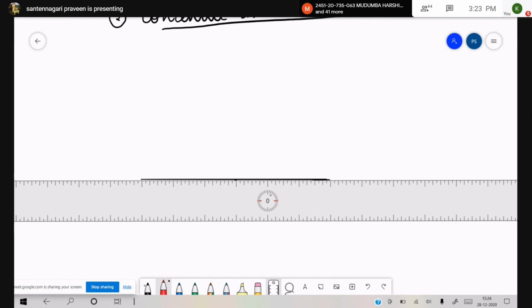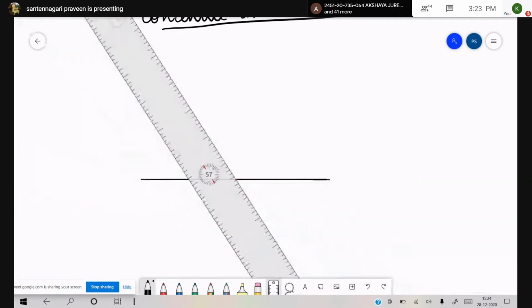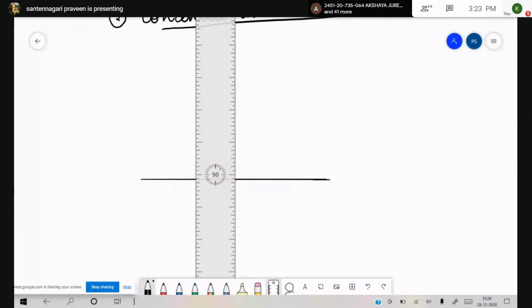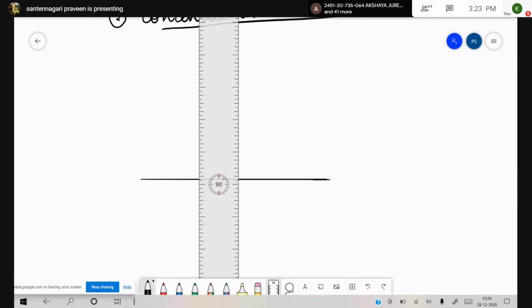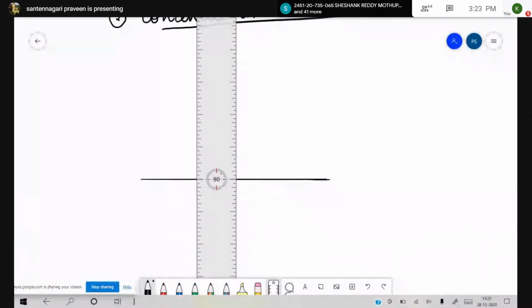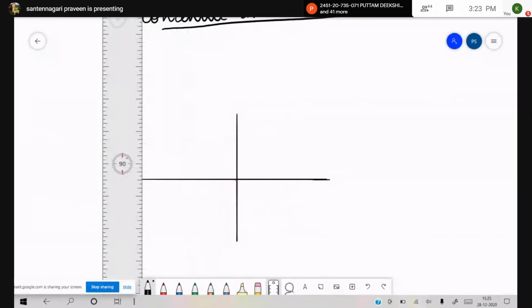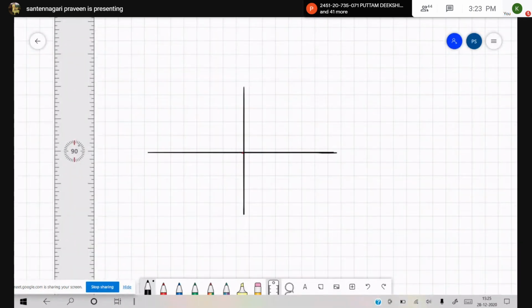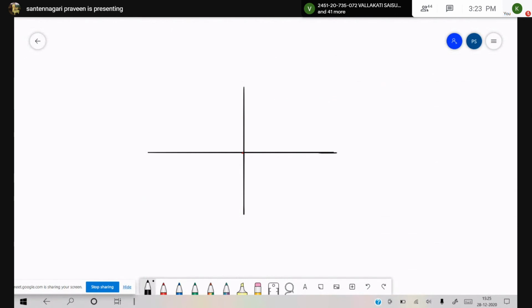This is your center point. So from here, the rest. Place this in the center. Your first half of your minor axis from here, and the rest from here. This is a way to draw your major axis and minor axis given measurements. Now, what next?